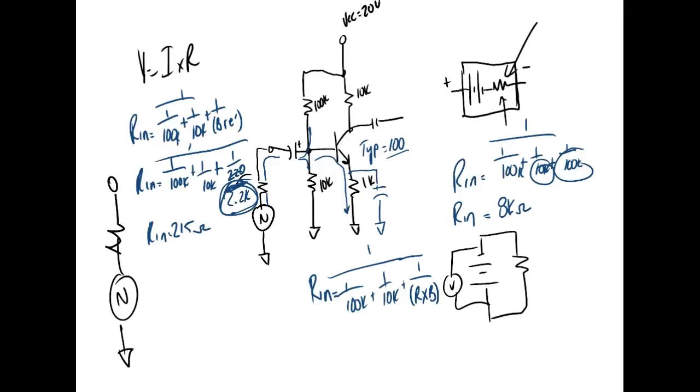Because power is equal to what? V times I. So that's one big advantage of a common emitter. You'll get both a what? If it's designed correctly, not if you just go out and throw stuff in there, you can get a current gain and a voltage gain. All right? So characteristics: input resistance, low. Output resistance, high. Phase relationship.